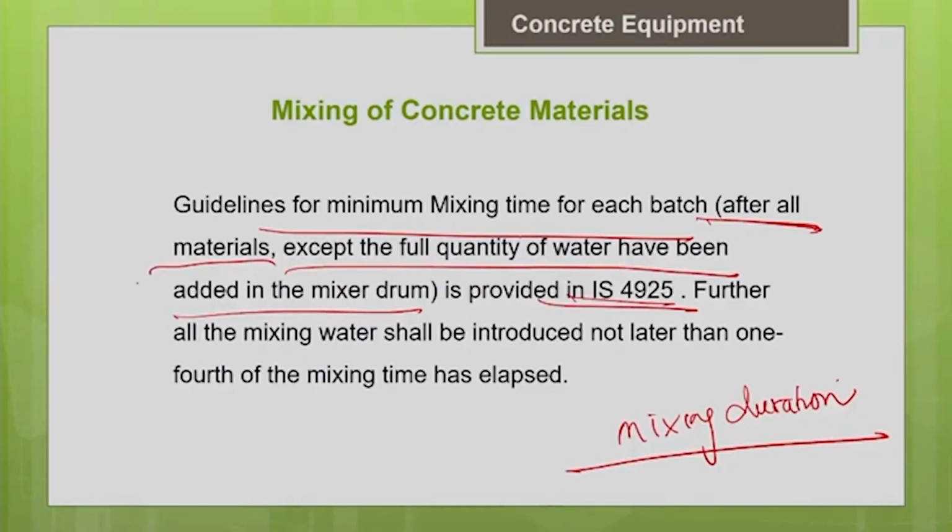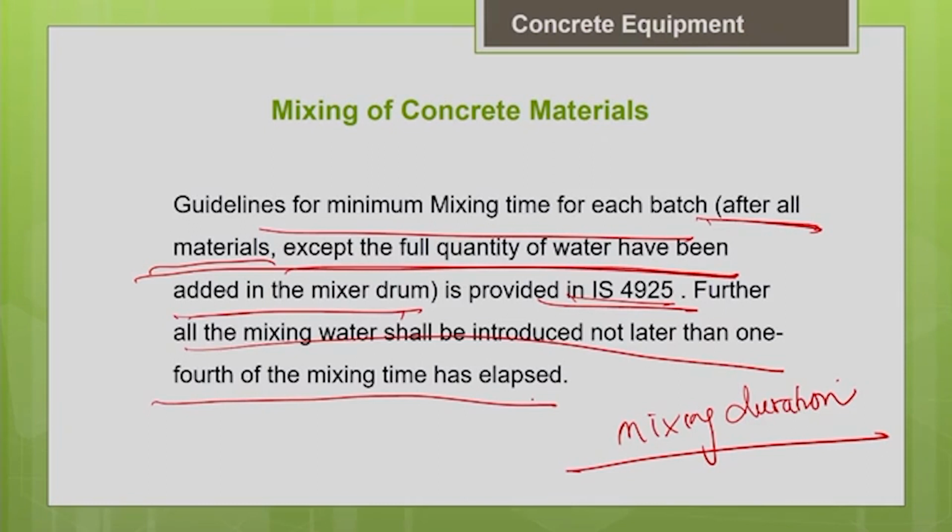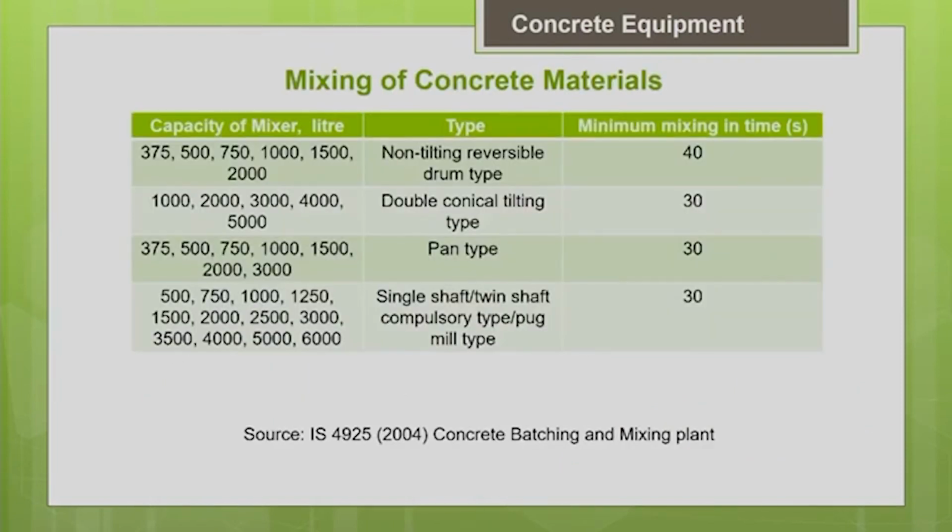After all the materials are added except the full quantity of water, your mixing time is taken into account. Another important thing you have to note here is that all the mixing water should be introduced not later than 1/4 of the mixing time has elapsed. That means, though you add the water in stages, the entire mixing water should be added not later than 1/4 of the mixing time has elapsed. This is a guideline available in IS 4925. We are supposed to follow the guidelines. So, this is what I told you.